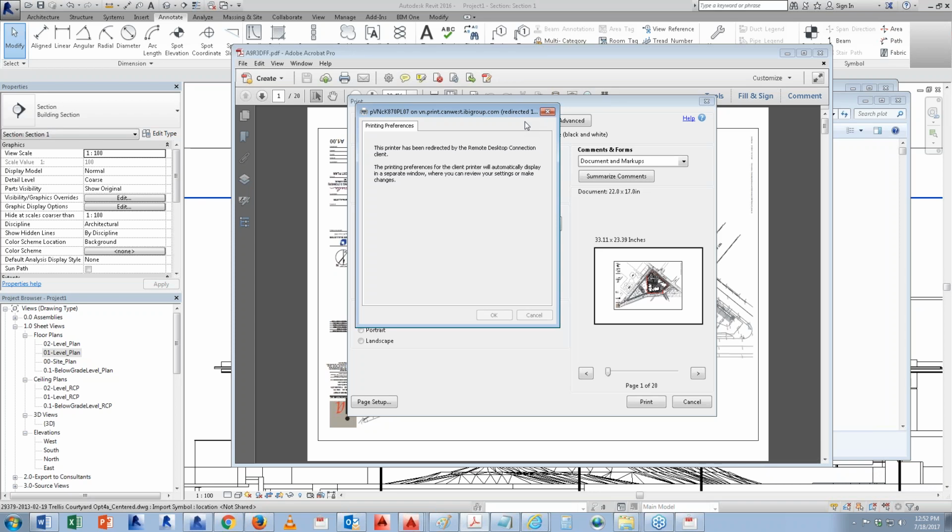Sorry, my graphics is really bad for this one. Choose the CAD and hit OK. And when you do the pen settings, use the line quality, okay? Those two combinations will give you the best result when you print out all your drawings. I would not choose other settings unless you have a really nice graphics poster, then you have to choose one of those photos or something else. But for CAD, these two settings are basically what you need to put in, okay?